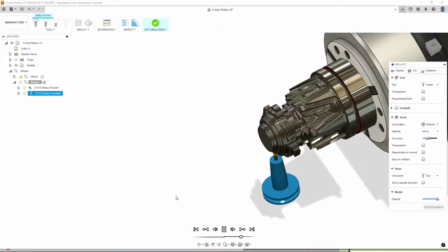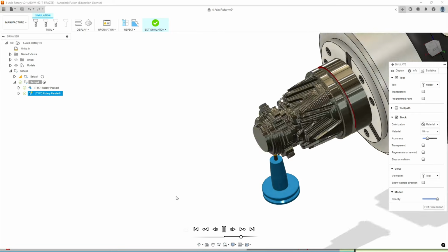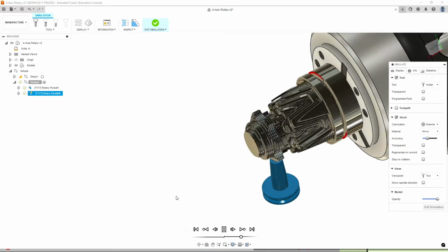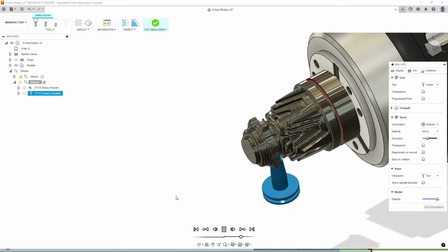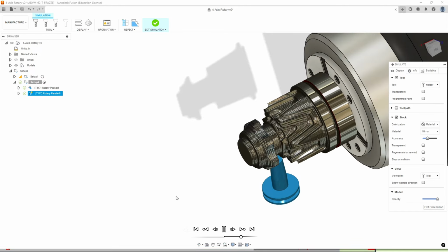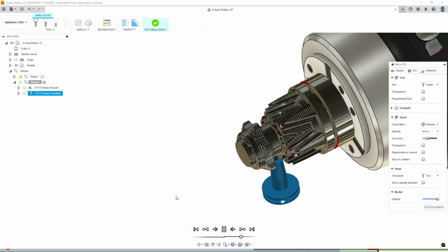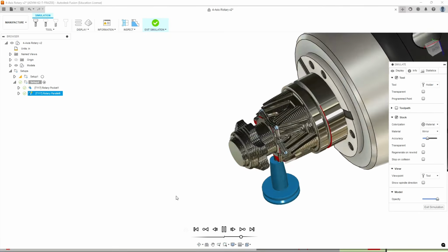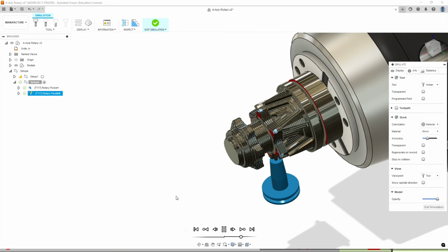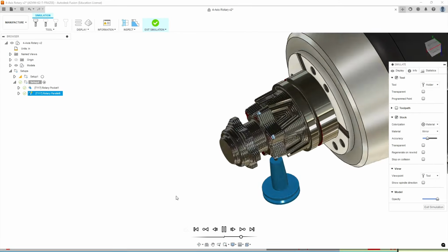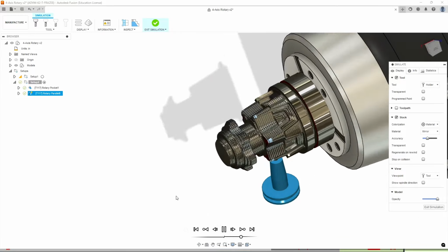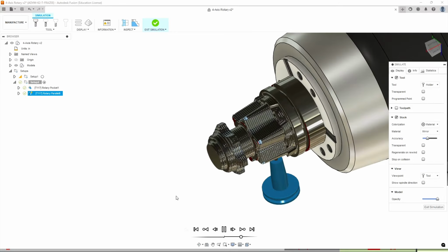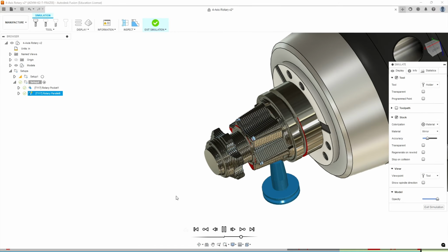Okay, so I skipped the roughing, but as you see, it's going around, spinning the part, somewhat like a phonograph record. Now naturally, if you're doing this as a true finish cut, you would want to put significantly closer scallops and perhaps go in with a smaller diameter than the roughing ball cutter to give yourself clearance at the end.